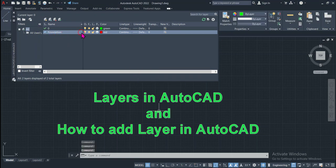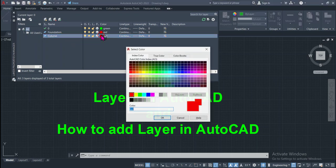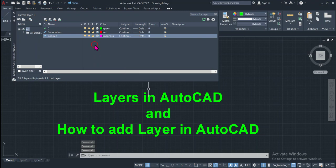So this layer is generated and we named it foundation. If we want to add another, we click here and we can assign any name to the layer. We want to name it column, and to assign a color, we click on the color. We want to assign a pink color to the column and then click on OK. A pink color has been assigned to the layer column.